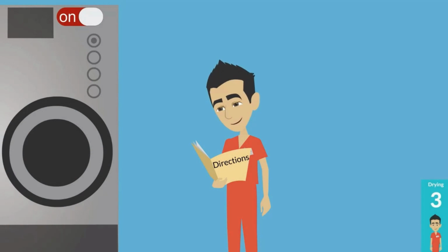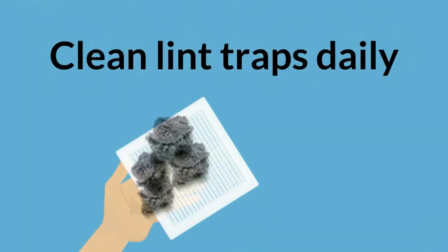These maintenance tasks are important. Clean lint traps every day, as this will improve drying efficiency. Clogged lint traps will result in longer and inefficient drying.